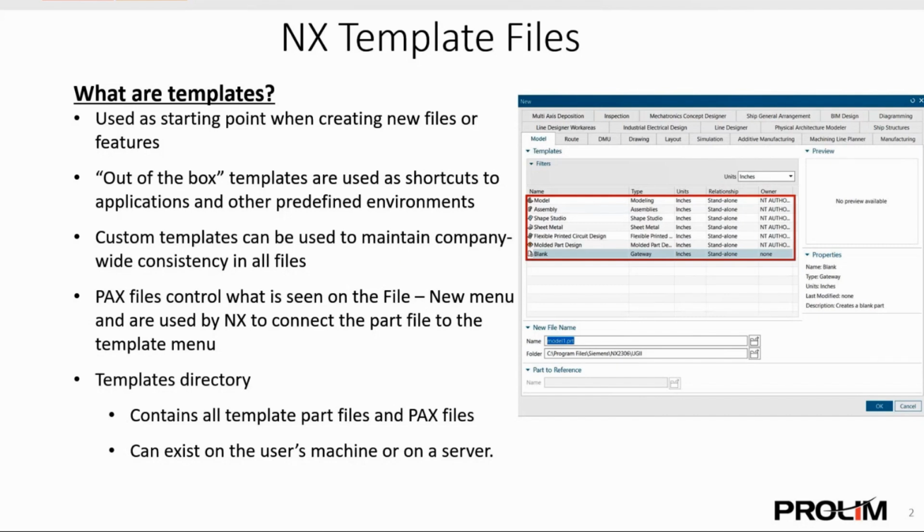All templates are controlled by PAX files, which help NX connect the part files to the templates drop-down in the File New menu. The templates directory contains all template part files and PAX files and can exist on the user's machine or on a server.